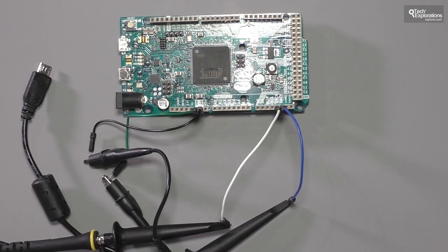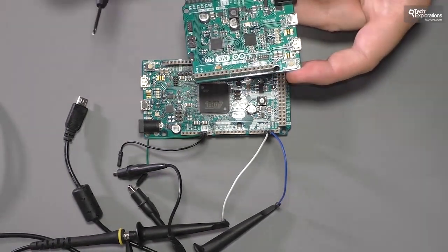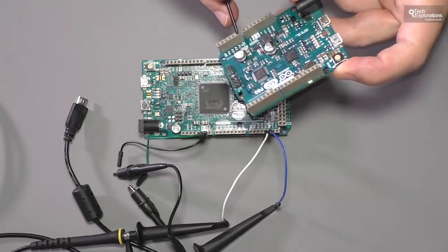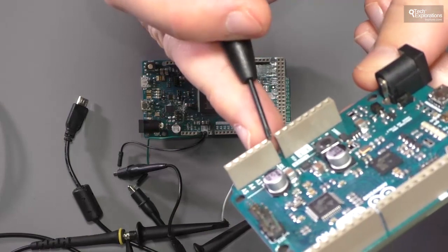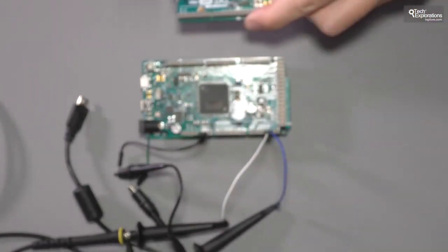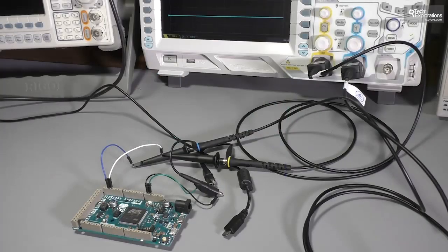As I said in the introduction, the Arduino Due has got two of them, DAC0 and DAC1. Remember that the Arduino Zero also has a true analog to digital converter. It's got a single one, exposed at A0. The difference between the Zero and the Due is not just that the Due has two of the digital to analog converters, but also that they are of higher resolution.